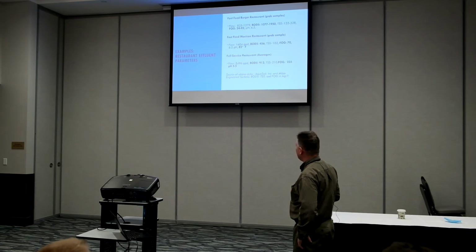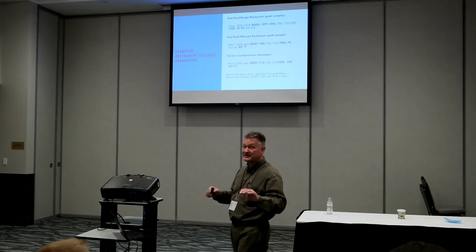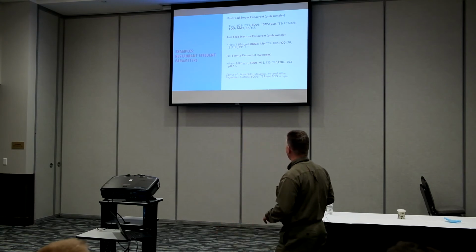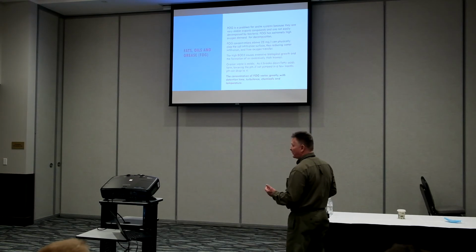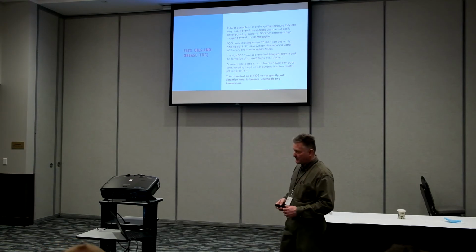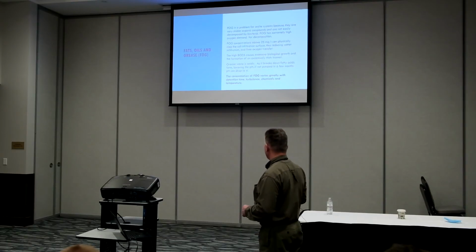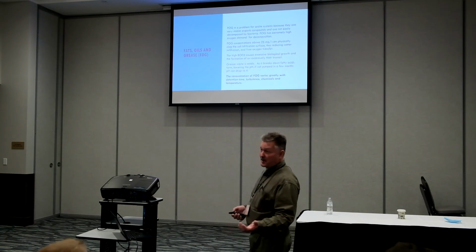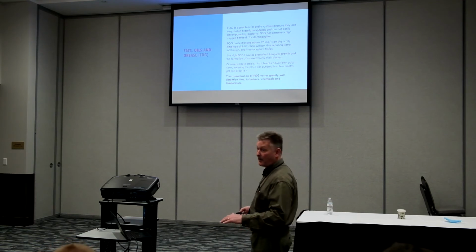So just to give you an example, when we're comparing that to our baseline measurements, we can be way up there and really put us out of the ballpark in design. Fat, oil, and grease is, again, a very stable organic compound. It's very difficult for the bacteria to reduce. The grease over time starts breaking down into fatty acids. And actually, if that tank's not pumped in a few months, you'll start seeing a big drop in the pH. It can go down to about 4.